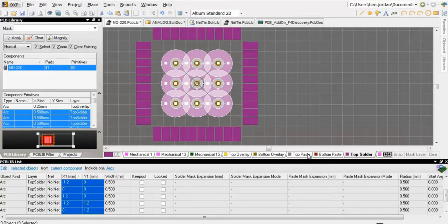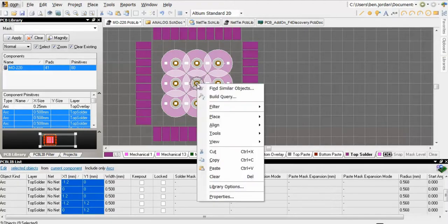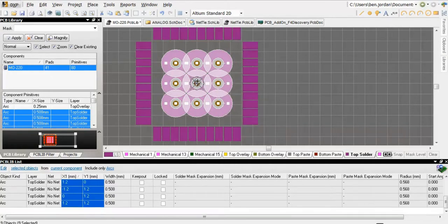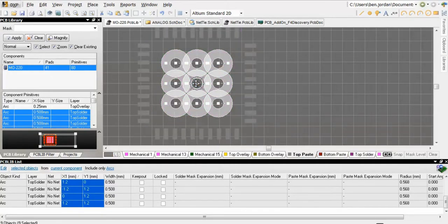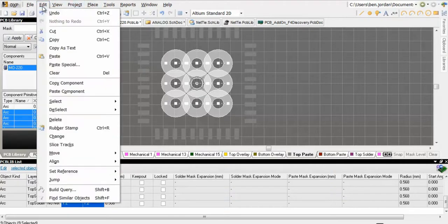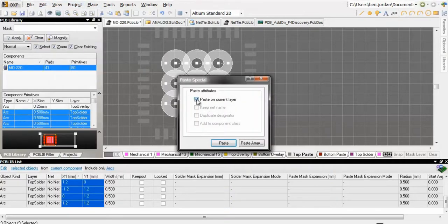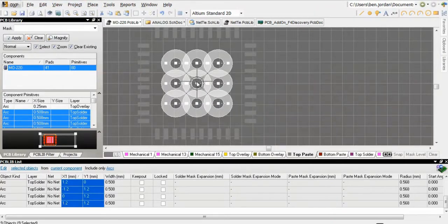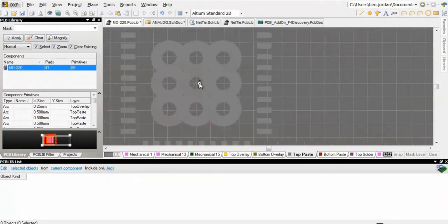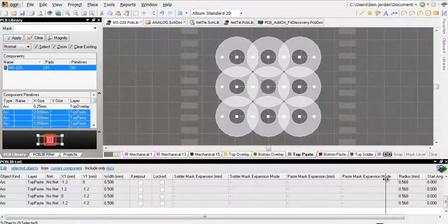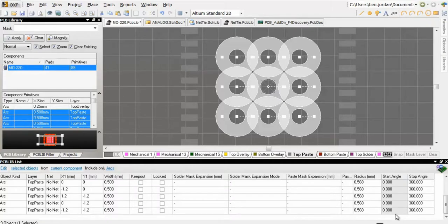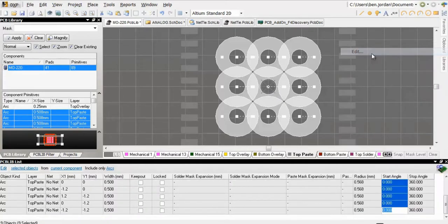That's way cool. Now I want solder paste mask openings which will place paste over the circles, but the solder paste stencil can't support donut centers. So I'll copy these circles to the paste mask layer, then using the List panel again, I'll edit all those to begin at 60 degrees and end at 220 degrees.